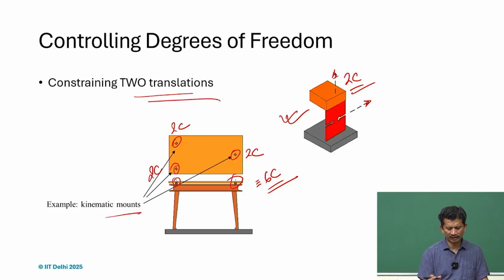6 constraints we can get, and we can get a very good kinematic mount. So, this is one of the applications, and if we place any sensitive instrument or a plate where it is very critical to have the precision, and we don't want to transmit any kind of torsional moment or bending moments there, then it's a very nice way to use, and it will get limited to these flexures, these members, and it just provides 6 constraints, and therefore is equivalent to any 6 constraint kinematic joints or kinematic clamps.